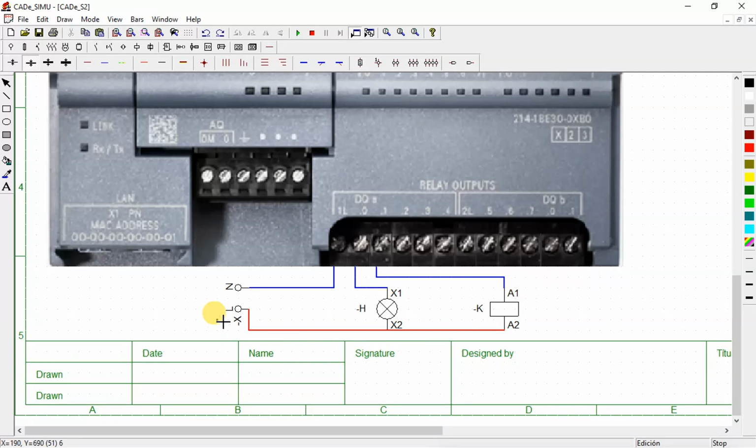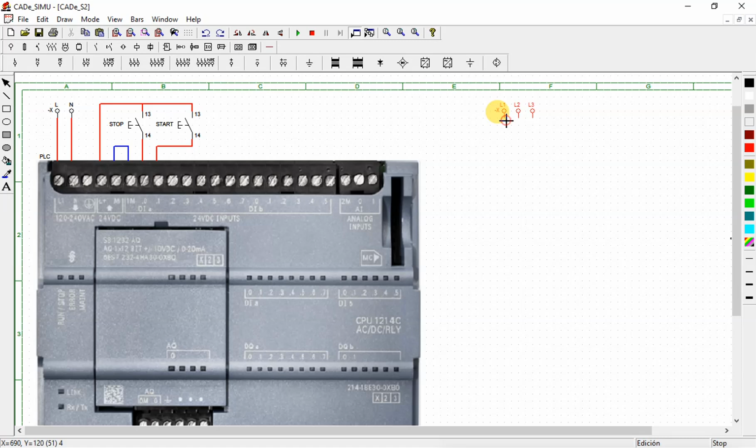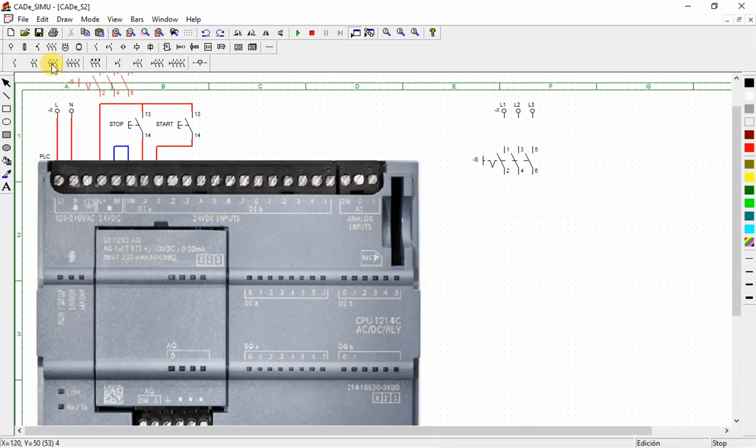Are you seeing? They're also sharing the same live, but with the neutral, it is these respective pins that are going to complete that normally open instance according to the ladder diagram. So that's how we do the connection. Now let's have a power circuit of our motor. For it, we can have here a 3-phase around here. Then we have our circuit breaker, then we have our contactor.